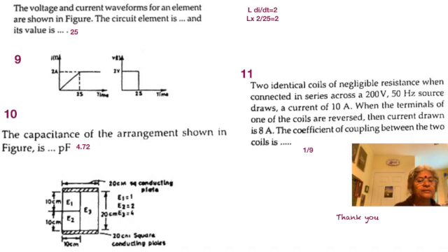So it's going to be C1 parallel C2, C1 C2 divided by C1 plus C2, and then you will also have plus C3, where C1 will have epsilon 1 and C2 will have epsilon 2, and C3 will have epsilon 3. You will have D1 and D2 as the same 20 centimeters, and D3 will be equal to 20 centimeters. Everything has to be converted to meter, and you will have the areas all the same, equal to 20 into 10 into 10 raised to minus 4.